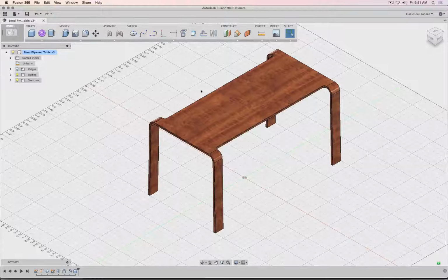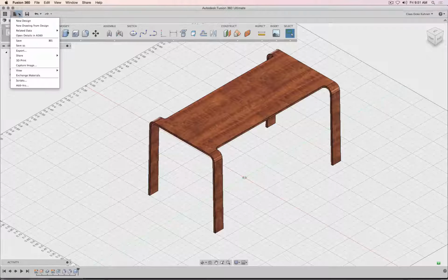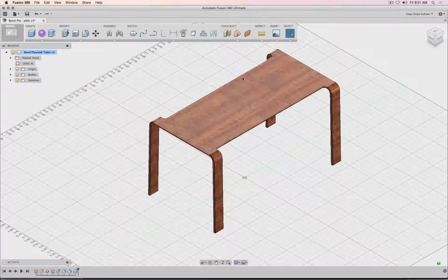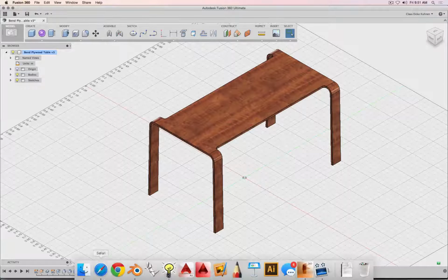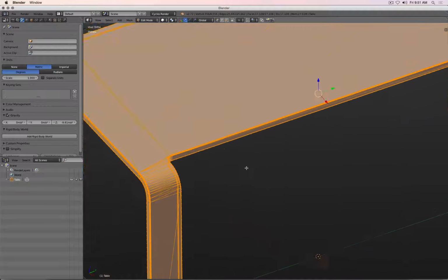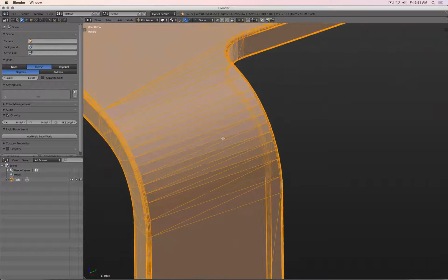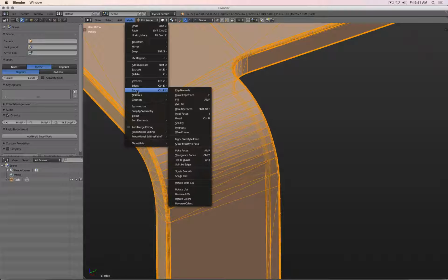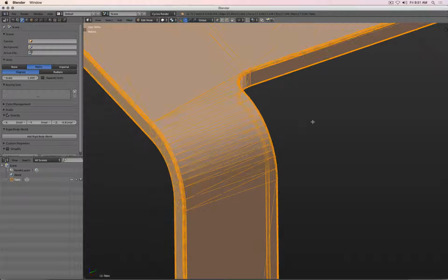So far I have showed you how we can select an object and then via the 3D print export our CAD model into STL and then import that model into Blender so we can better texture and render it. The process is pretty doable, works, but the problem is we end up with a triangulated mesh. That is, for example, why in previous videos I then went to faces and set triangles to quads.